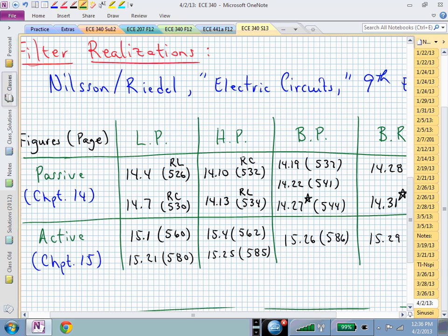And if I said, oh, sketch me a low-pass filter, hopefully you're all thinking about this RC that we've done in the past. You have a resistor and then a capacitor, and we're measuring the voltage across that capacitor, and the input is the voltage impressed across that series combination of resistor and capacitor. If you wanted a high pass, now you just flip the 2 elements with each other and you have a CR, and now you have a high pass type filter.